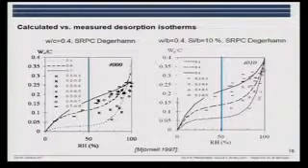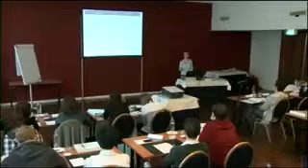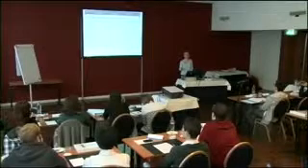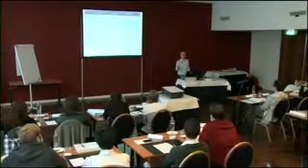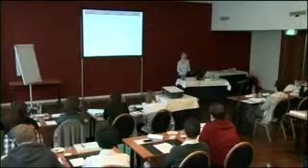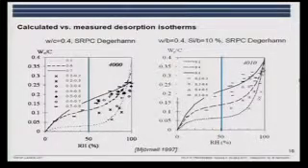I should say that I have added some slides, and when we upload the presentations, you will get copies of these. If you compare here, you can see that it seems that we have more gel when we have the silica fume. And can you explain why? Yeah, we have the pozzolanic reaction. Yeah. So we have more CSH. Okay.